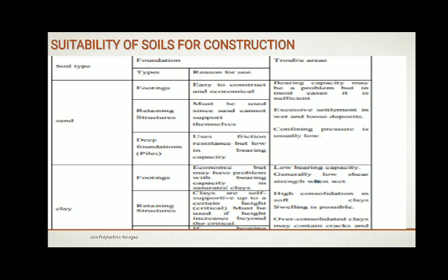Now coming to the next soil type, that is clay. If you are using clay in footings and retaining walls, obviously as with sand, clay is also economic but may have problems with bearing capacity. Clays are self-supportive up to a certain height, and must be supported if the height increases beyond the critical. So clays have low bearing capacity and generally low shear strength when moisture enters the soil.